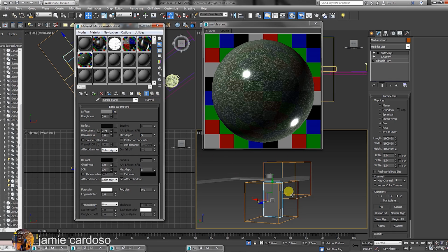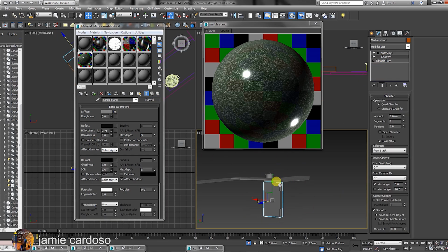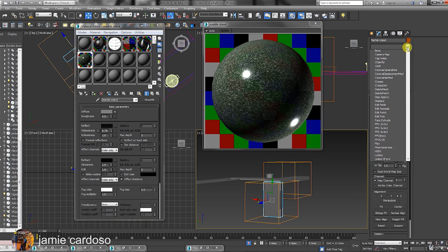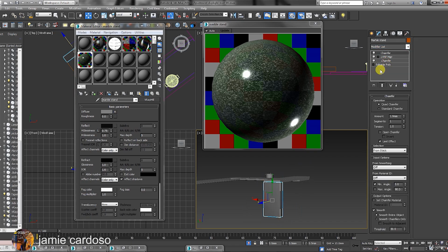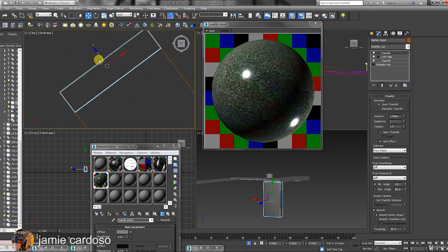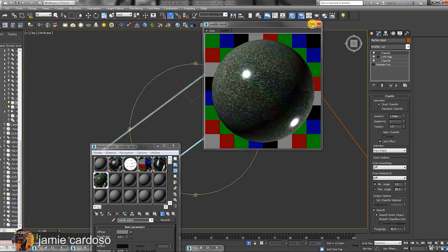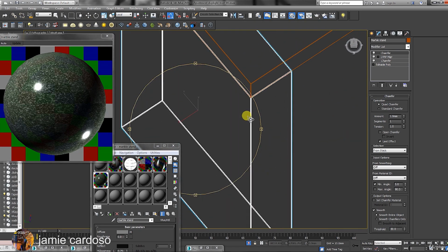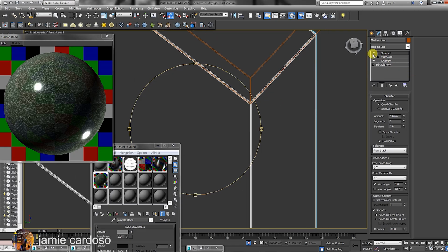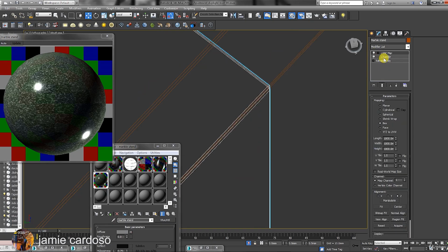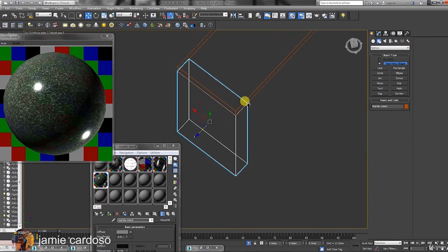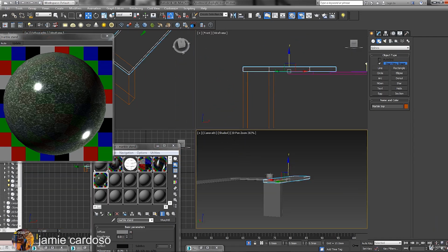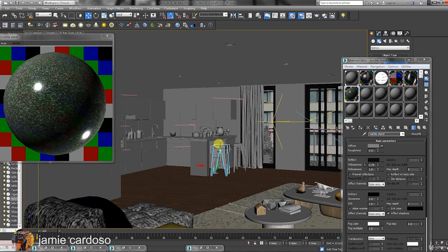In the Modify panel, there's already a chamfer modifier applied to this object. It was originally applied by going on the modifier list and choosing chamfer from the list. In the real world, most objects are not 100% sharp. The chamfer modifier is often applied to bevel the sharp edges of objects, making them more realistic. These chamfered edges will also be useful to pick edge highlights. As you can see, the chamfer was applied before the UVW modifier. Let's exit the isolation and the 2D zoom mode.